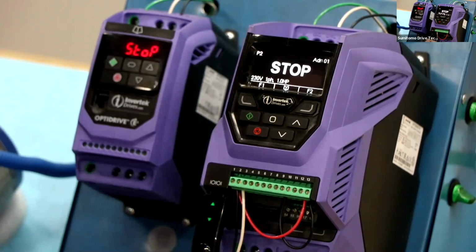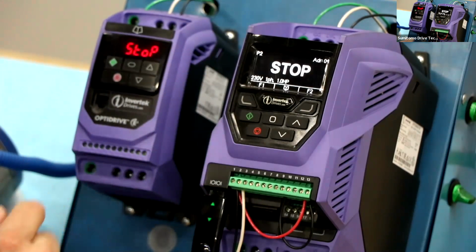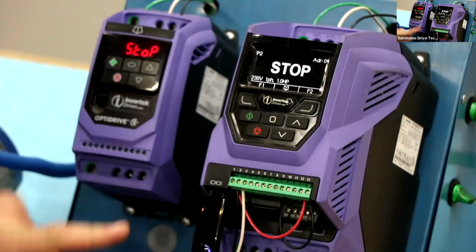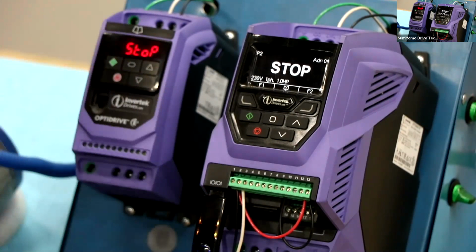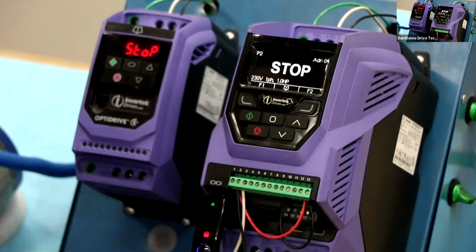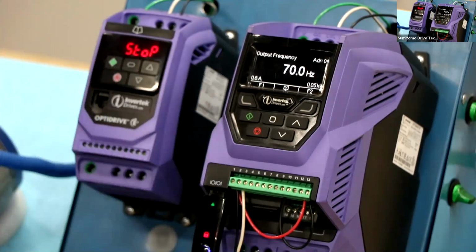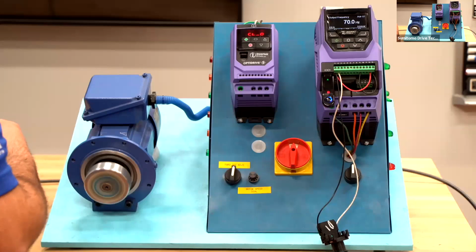And what we want to do is upload the parameter set to the drive itself. So we're going to tap the upload, and you'll see the lines are going towards the drive and it is now transferring the parameters that we created. Now, part of those parameters was the PLC. So that's on there as well. So now when we hit our start button, which is this key here, you'll see it goes to 70. I'm not doing anything. The computer's not doing anything. It's all being done by the PLC inside there. So you'll see it'll speed through 70 down to 20.